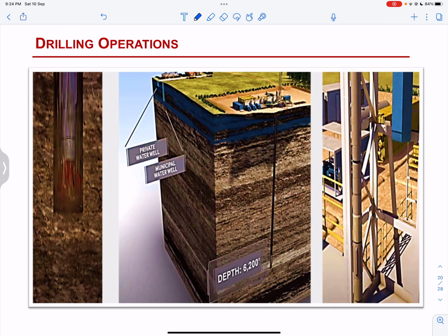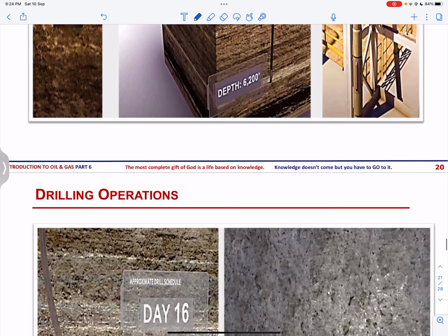Next, a small drilling assembly is passed down through the surface casing. At the bottom of the casing, the bit drills through the float equipment and cement, and continues its journey to the natural gas target area as deep as 8,000 feet below the surface.